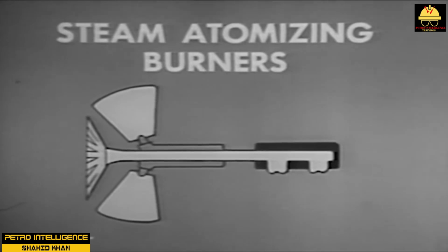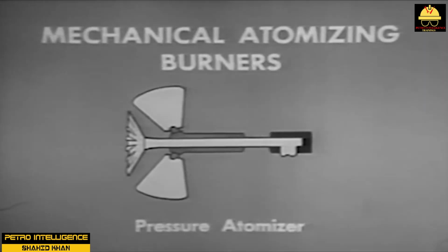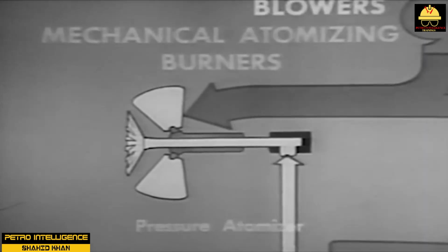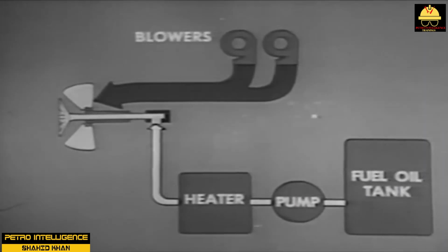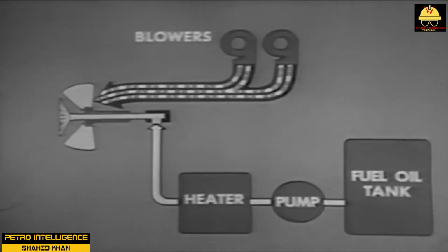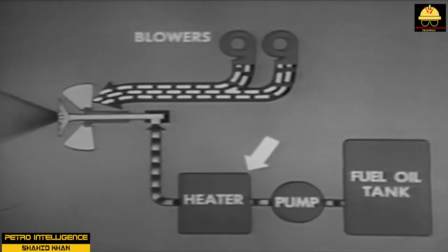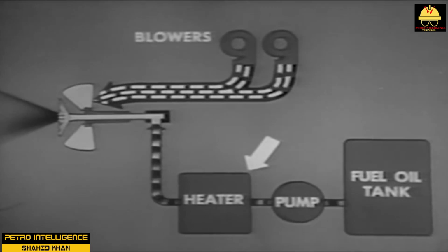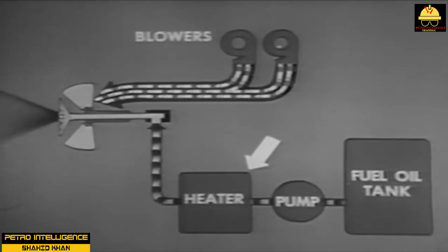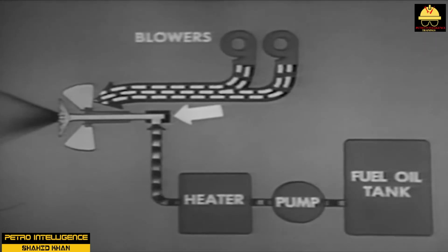Premix burners pull in primary air for combustion through a Venturi-type air-fuel mixing device. They respond to changes in firing to keep the air-to-gas ratio relatively constant. Secondary air registers are provided in premix burners. Burner alarms are located on each burner and will immediately alert a technician when a burner goes out or is functioning outside normal parameters.